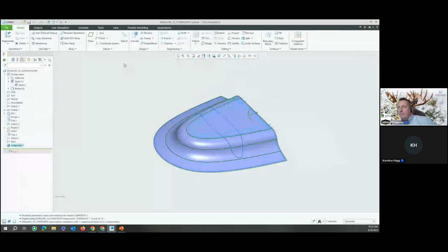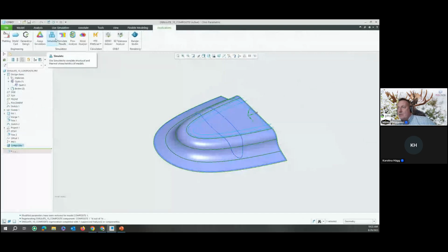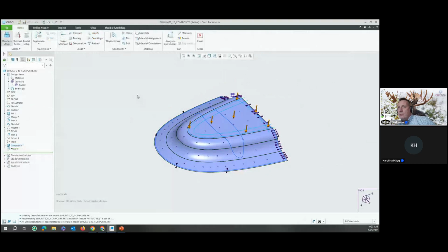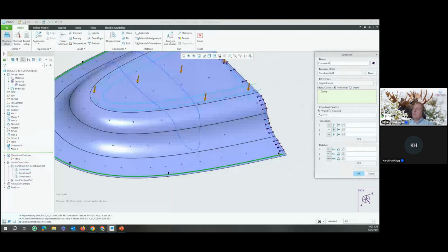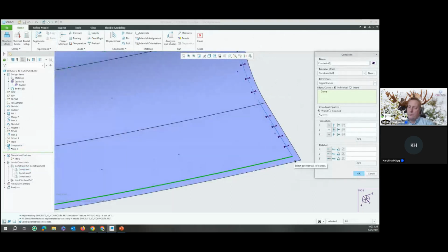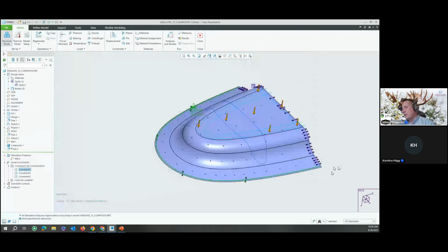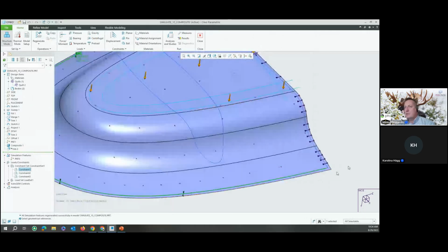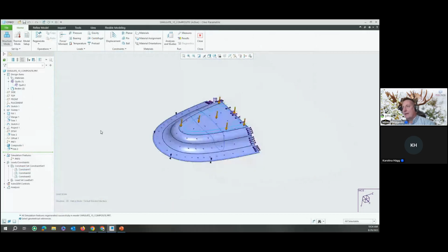Then when you jump from here to Creo Simulate, the PTC application, you can also put your forces and your constraints and whatnot in here. One thing I learned by myself by making mistakes, of course, is that since this is defined so that you have your basic quilt, which you use for making the layup, you also have a kind of boundary curve for that. And you actually use that very curve to define the boundary conditions. If you use a modeling operation like a trim and cut away the excess material in here, and then use the edge of this quilt, then the system basically fails for you. So you can't really get anywhere.